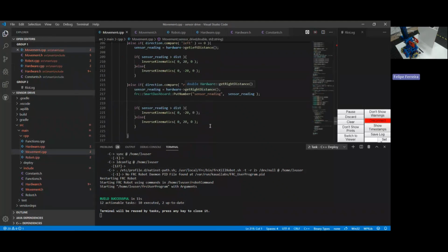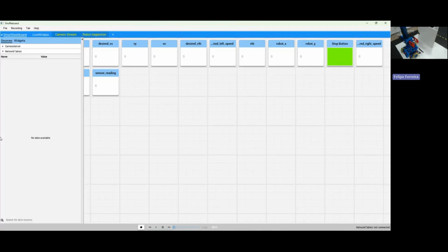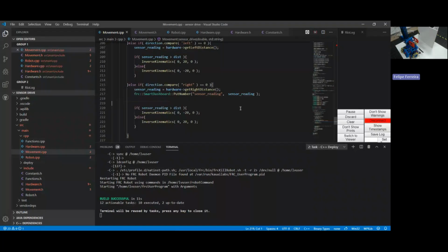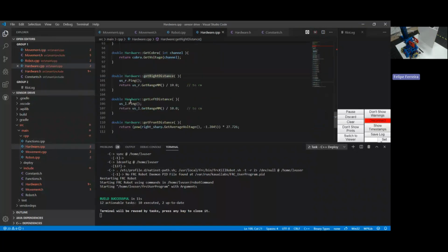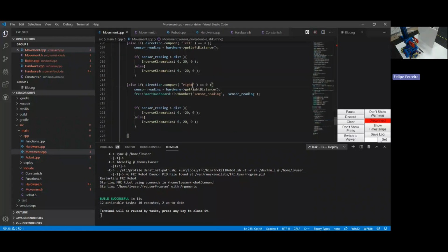Okay, so now I'm sure. I don't know if you realized before, but what was happening is that it measured the ultrasonic one time and did an update, so my robot was stuck with that first measurement. Now that I have the ping function here, it will keep updating.